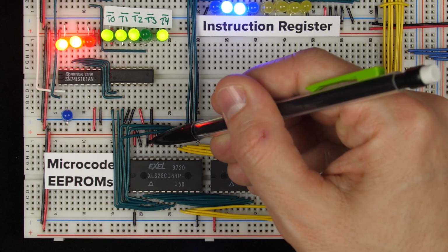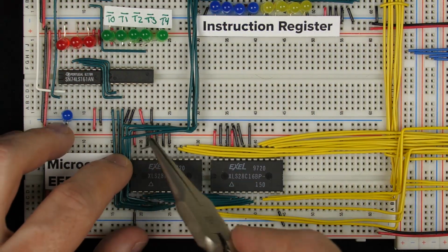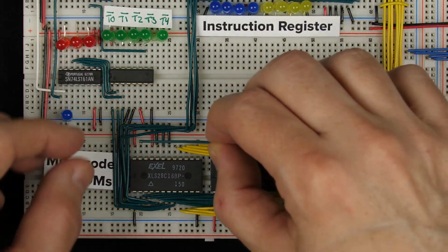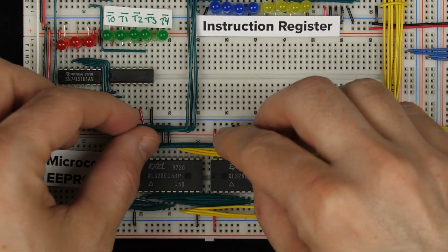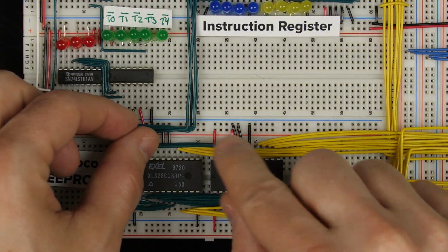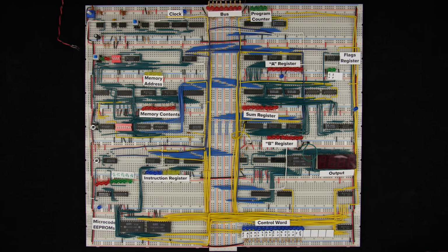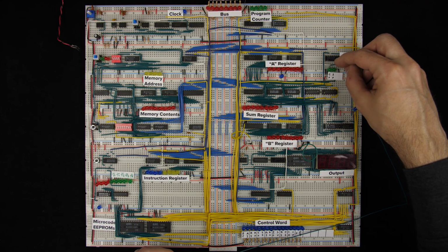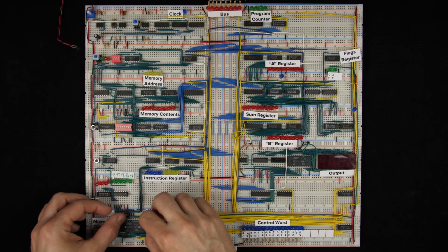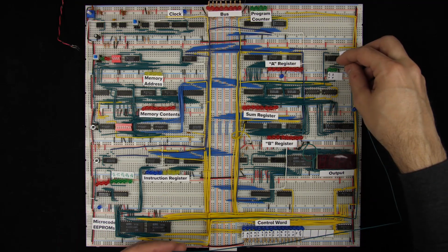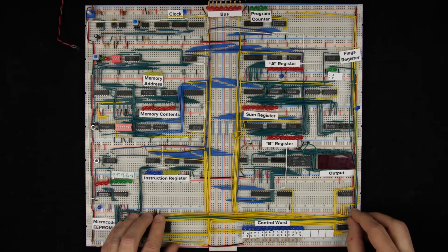Address 8 and 9 are these 2 pins here and these 2 pins here, and they're currently tied to ground, so I'll remove that to start with. Next, I'll tie address 8 on the left EPROM to address 8 on the right, and address 9 on the left to address 9 on the right, since we want to consider the flags register the same for both halves of the control word. And then let's hook the carry flag over here around to address 8 of the EPROMs. And same thing with the 0 flag. I'll hook that up to address 9 of the EPROMs.